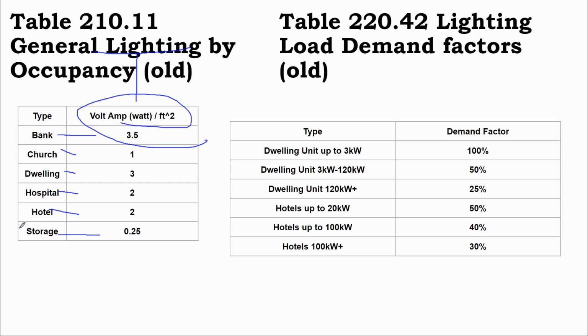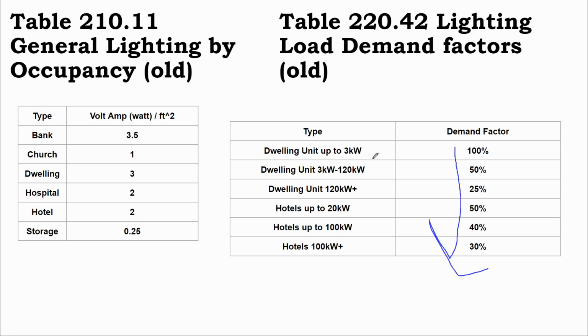And that is useful so that you don't get thrown for a loop from one building type to another. We also see that these load calculations are substantially reduced the larger the facility gets, because it's assuming that not all of those loads are going to be on at the exact same time, and it's seeing some benefit from aggregating multiple users onto kind of one grid feed.